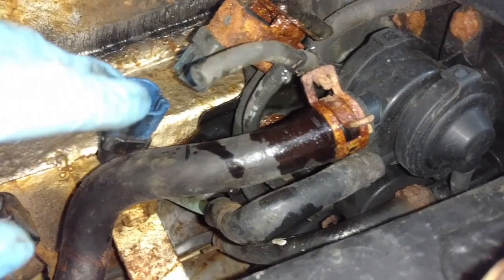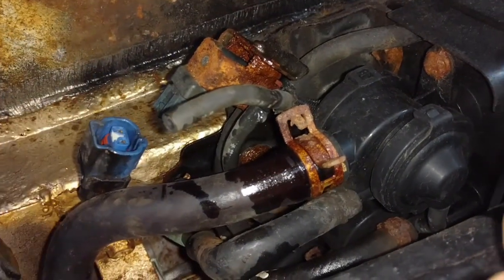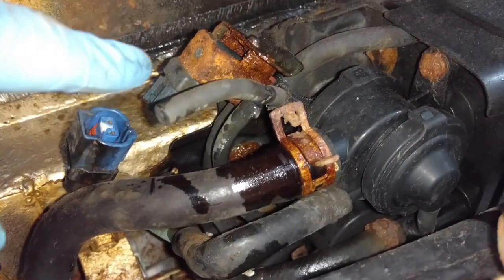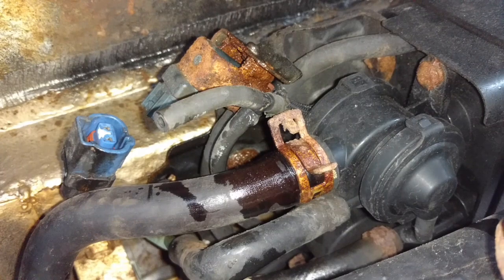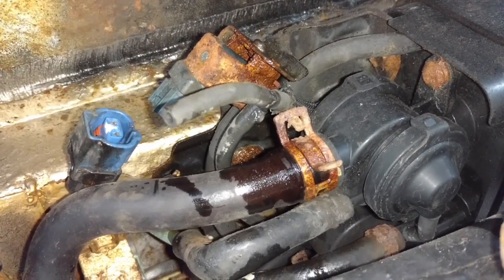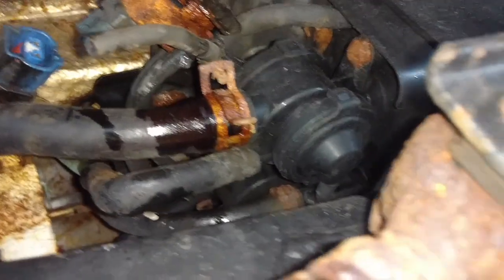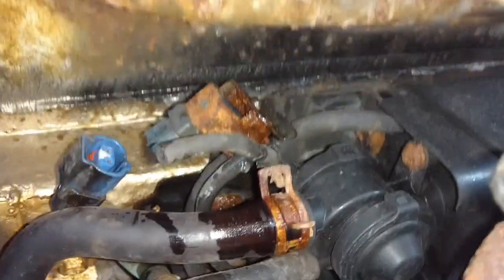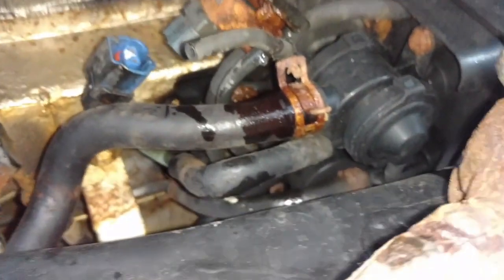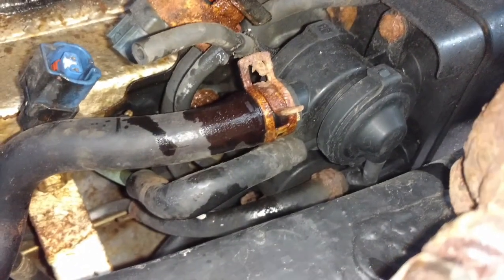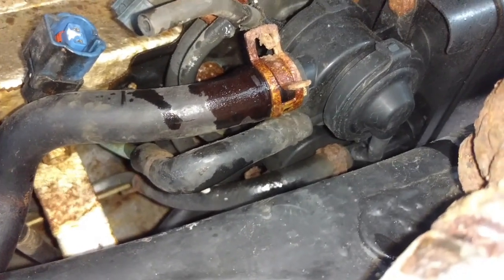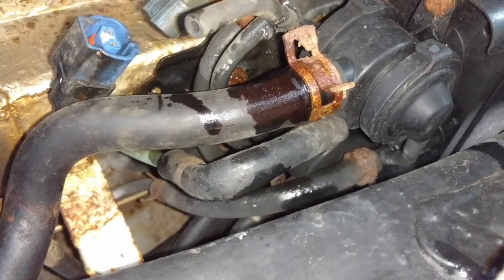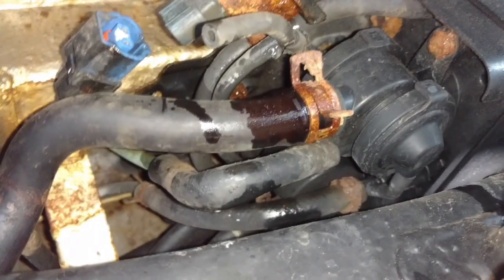By the way, I checked with the ohm meter and with the 12-volt battery using this. I hear the clicking, so it is working itself, but we don't know if it is clogged or not. Maybe some other problem. Anyway, then we have to remove this charcoal canister. After that, we need to remember these hoses, some of them are the same size, so maybe take pictures or make marks to put them in exactly the same location.